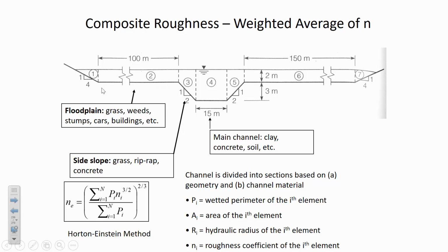surface that's not moving. And so you can see that you multiply the wetted perimeter of any segment by the corresponding n value for that segment, and you add them all up, and then you divide by the sum of the wetted perimeter. So if you have a really long 100-meter segment, in this case, of a high n value, then you'd multiply the 100 meters by whatever the n value is for that segment, and then you'd break each of these pieces up into any place there's a different n value. You'd calculate the wetted perimeter individually and come up with a weighted average in that way.